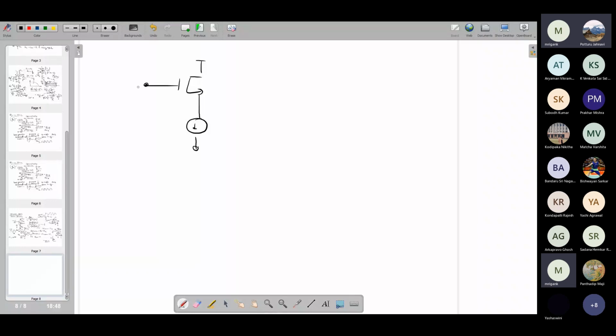Now you have a voltage source. Now this is a common source, common gate amplifier, whatever, which is having a sufficiently large R out, and this is your V in, or rather I should not call it R out, it will confuse you. So this is R signal. The previous stage can be anything. It can be common gate, common drain, cascode, whatever. Which is providing a sufficiently large signal, and you are also getting a large R signal. So definitely I need to be concerned about the capacitance at this node, because this R signal can be large. So this is going to give me one critical pole.